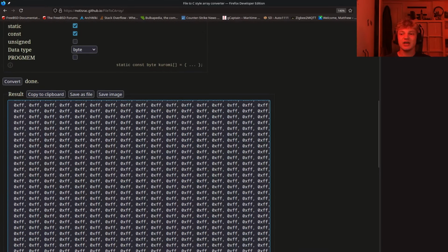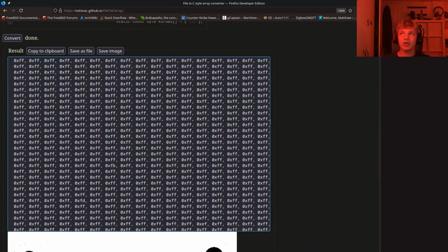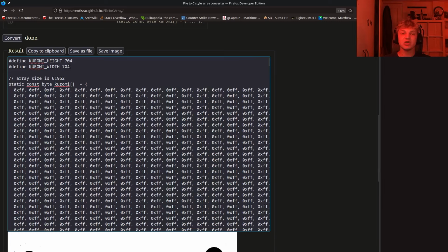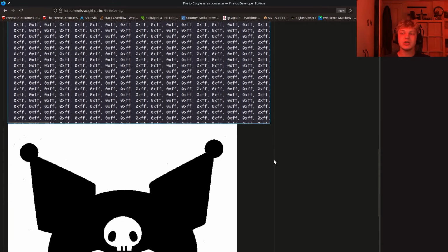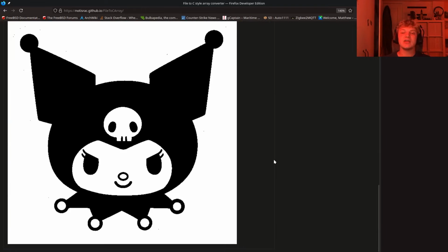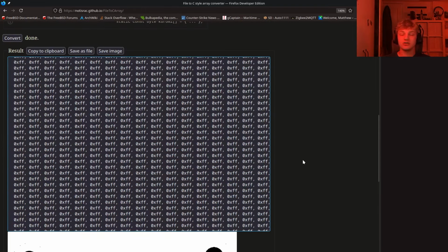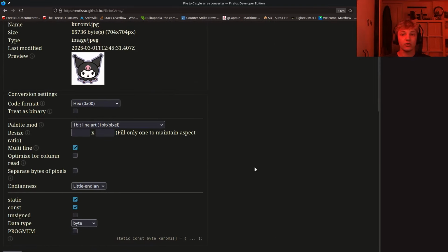So essentially, if you want to render a bitmap, think about this. This is a massive, massive thing to know. If you want to render a bitmap, all you need to do is directly copy it into the frame buffer. Because if you think about it, this is essentially already in the perfect frame buffer output form. We simply have to copy it to the frame buffer and then send that off to the display driver in order to actually render that on the screen.